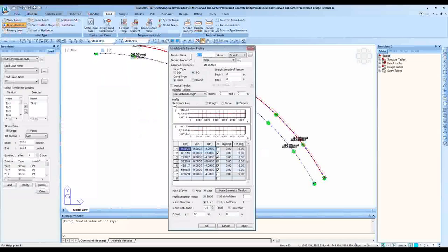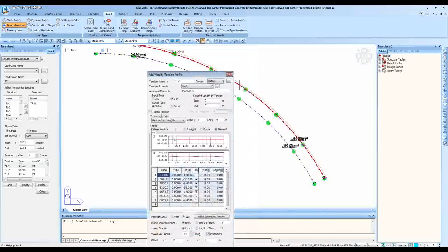So you can specify the tendon name. Basically, remember, you can actually choose the type, hub or curve, in the structure main menu. When you do it, it's going to create this type of individual coordinate data. And also you can, from scratch, just define the data with the coordinates too. And here, choose the tendon property and choose the assigned element.